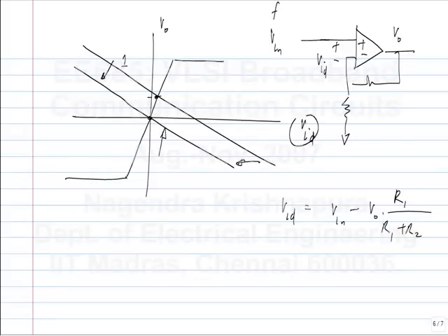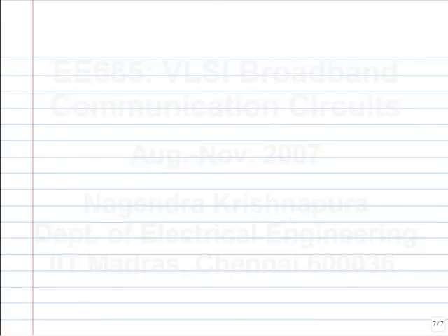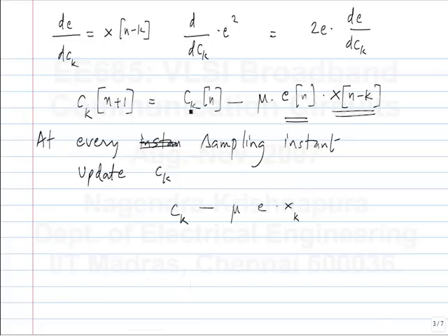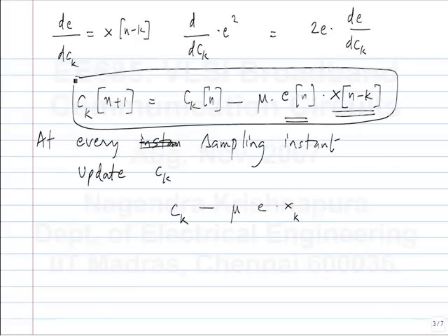It's very simple. Now, how do we implement something like this? So, we have this and we have to implement this equation. How do we do that? Let's say we have some cell which has variable coefficients. That's not a problem. Just like we made it for the transmitter, the coefficient can be realized as a transconductor, as a differential pair with variable tail current or something. So, we know how to realize variable values of Ck, okay?